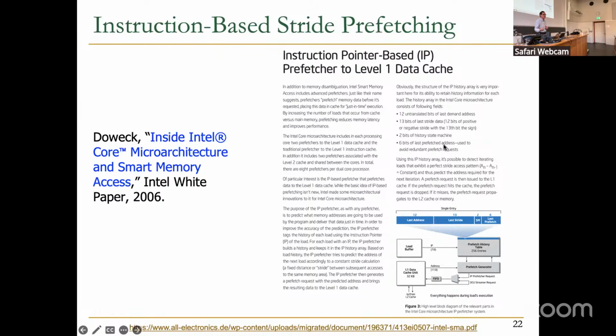So they need a very accurate prefetcher, because the L1 data cache, as we discussed earlier, is very sensitive, right? A lot of the decisions we make in how we design an L1 data cache are really dictated by the pipeline, because it needs to be tightly integrated into the pipeline, and you need to get data very quickly to supply the load instructions so that you don't stall the pipeline, right? And as a result, L1 caches are usually small, with very few cycles to access, and you need to manage the budgets of hardware very carefully. So if you prefetch inaccurate things into L1, you're going to reduce the hit rate in L1. So Intel actually implemented this IP-based prefetcher.